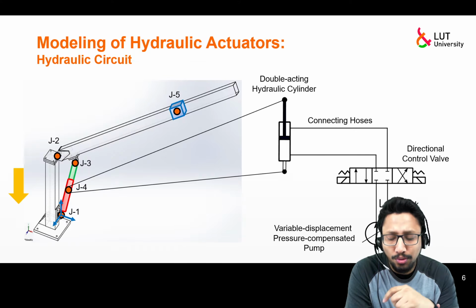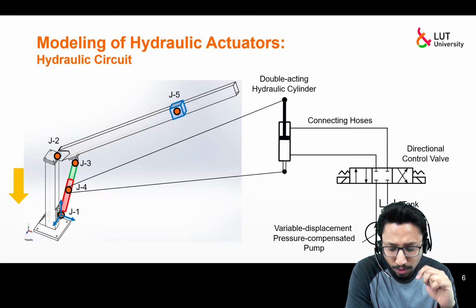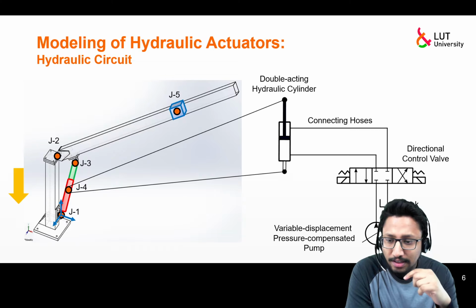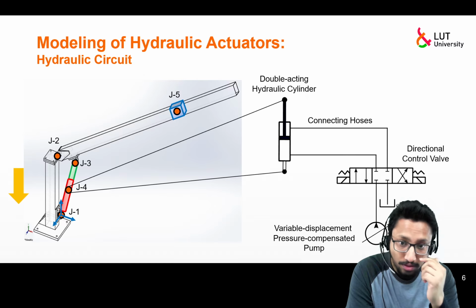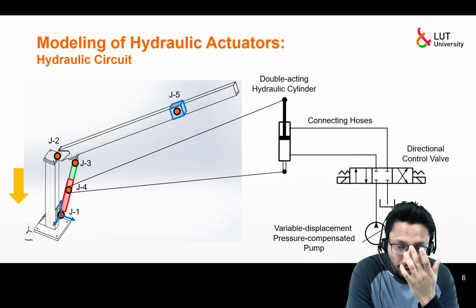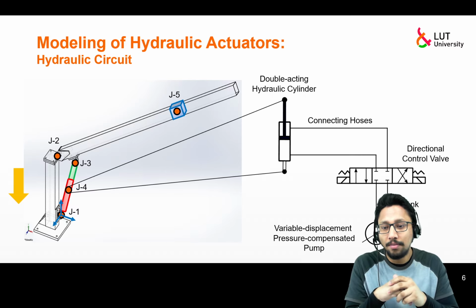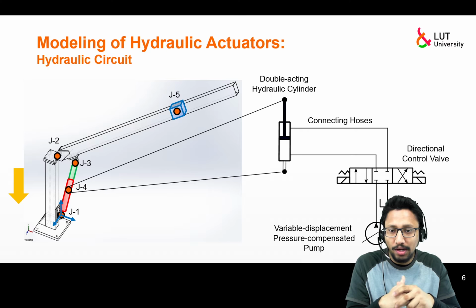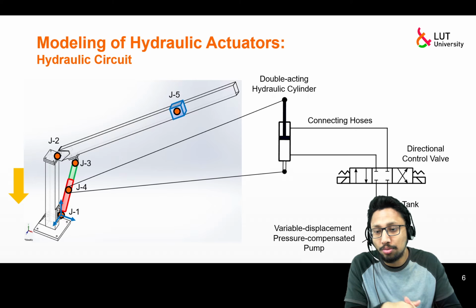In Simscape Multibody, if you go to Analysis, Simscape, and then the Statics Viewer, there you can see the degree of freedom of the system and any redundant constraints. Make sure that you do not have any redundant constraints, and the degree of freedom needs to be 1.